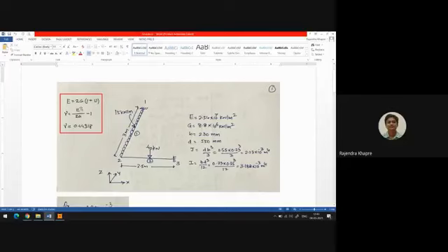I can substitute the value of E as 2.54 × 10^7 and the value of G as 8.8 × 10^6, and accordingly I have calculated the value of mu. Mu is nothing but your Poisson's ratio. The mu value comes out to be 0.44318. Why have I calculated this? Because I have to give mu as an input, and giving the value of G as an input is not possible in SAP. So let us start modeling this particular problem.